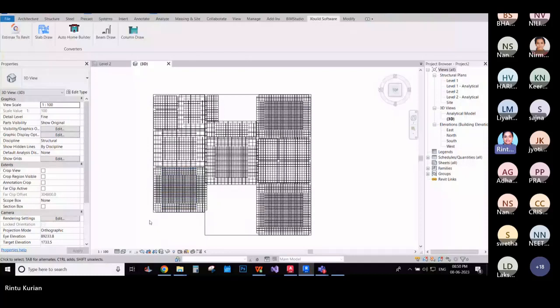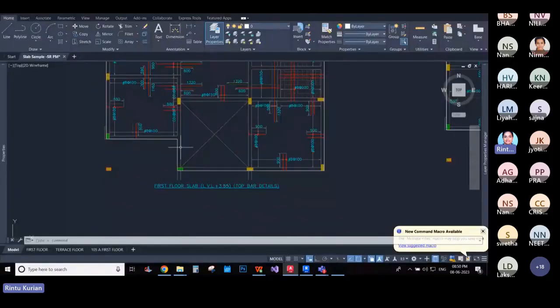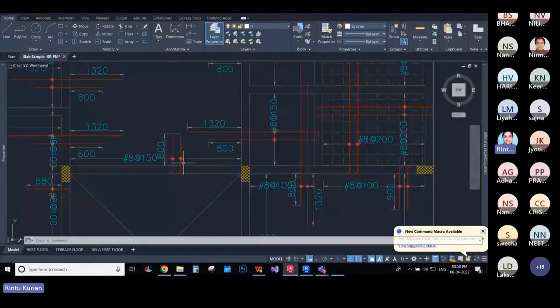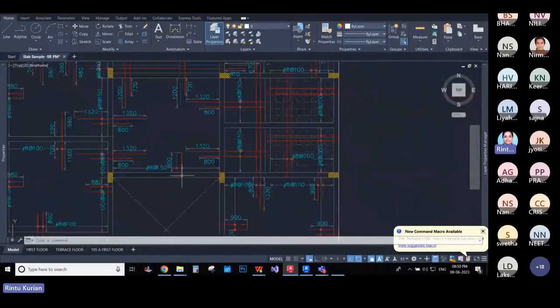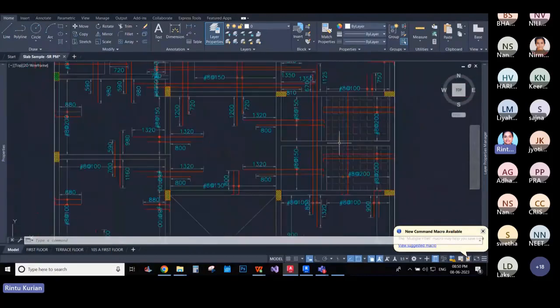Okay, now we'll move on to the rebar modeling of the top bar. And when it comes to top bar, I have said earlier that we have the L-shaped bars and U-shaped bars used here. The problem with these bars is that we can't directly bring them to Revit with the current situation of the plugin. We are researching easier methods to bring it directly, but at this point of time, we'll have to just explore the same.